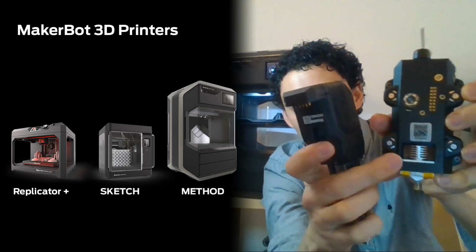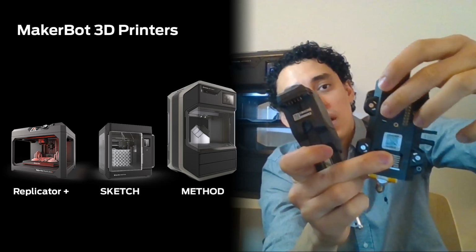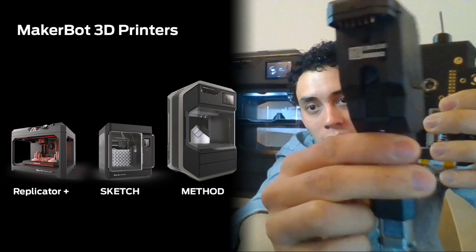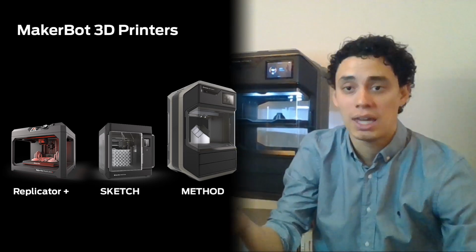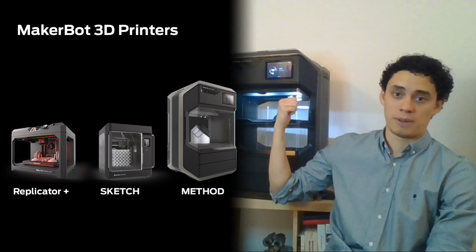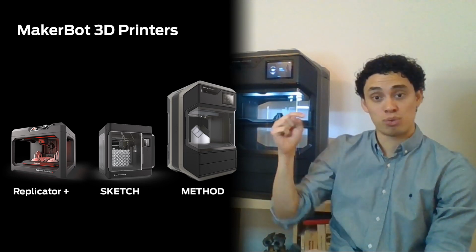If I look at the back, the regular Replicator extruder has only this wheel that attaches to the stepper motor in the carriage to push the filament through. With the Method extruder, you actually get a full gearbox inside of the extruder, and it's quite literally a gearbox that attaches to the encoder, to the stepper motors in the carriage, and amplifies the force that the carriage has to push the material through.